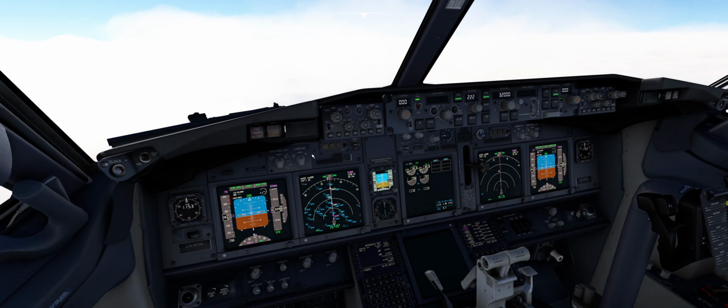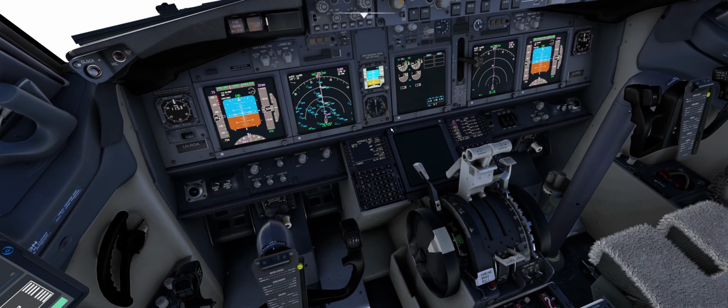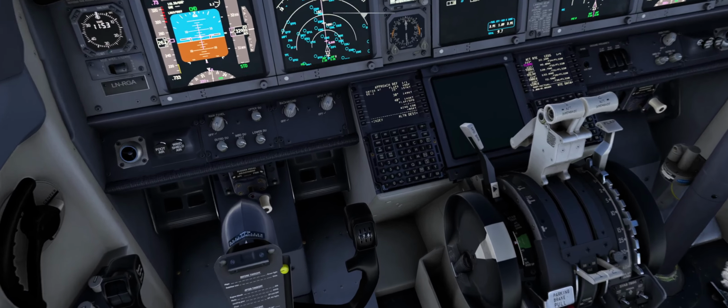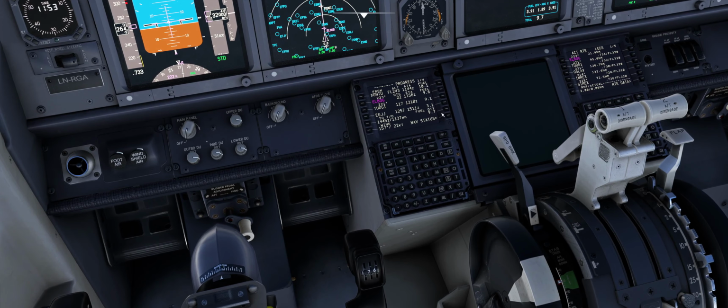And the landing preparation, except if I omit all this stuff like FMC, auto brakes, MCP and now settings, one part is related here. So as you can see, we have 9.7 actual fuel on board, and on the landing we are expected to have 3.1. So we are going to burn approximately 4.6 tons of fuel, so you will need to adjust your gross weight. Okay, so 62 and 61.6.